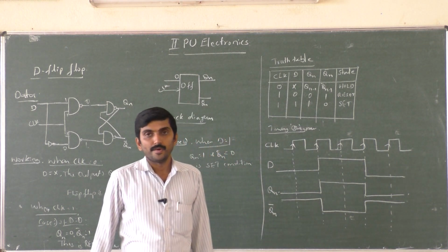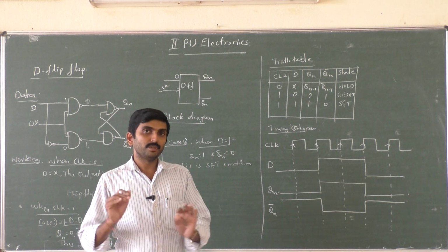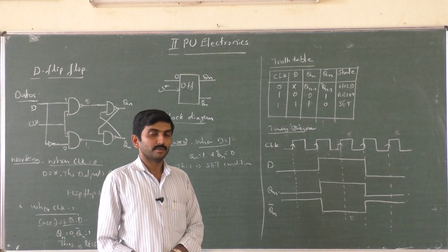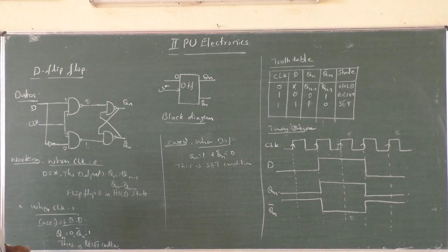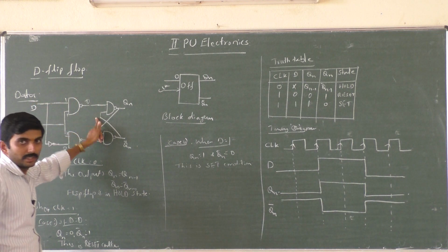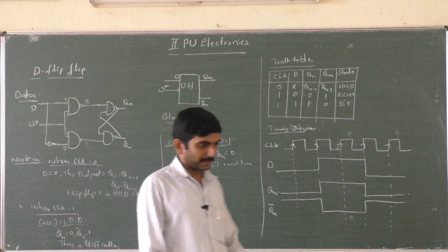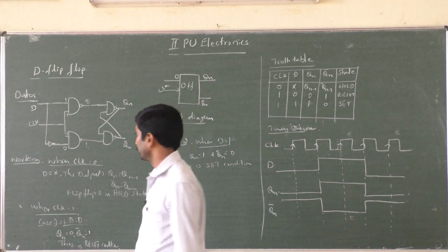See, very very simple working of the D flip-flop. An inverter is connected in between S and R of the flip-flop, and the S input is extended to give the D input, and a basic NAND latch is used. That is the brief circuit description of the D flip-flop.